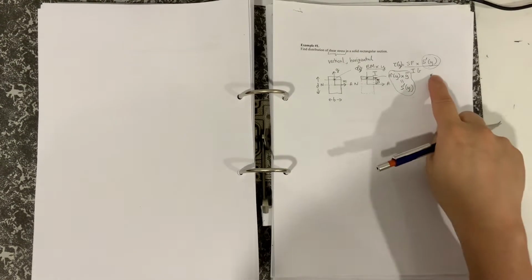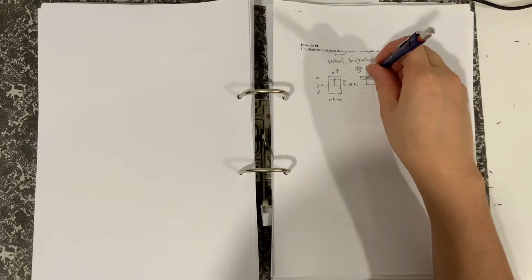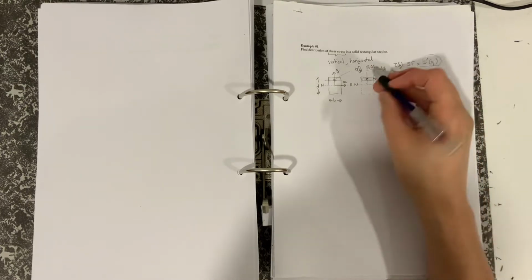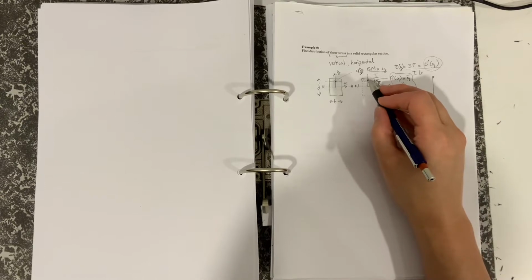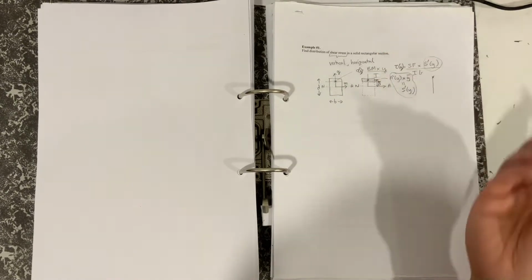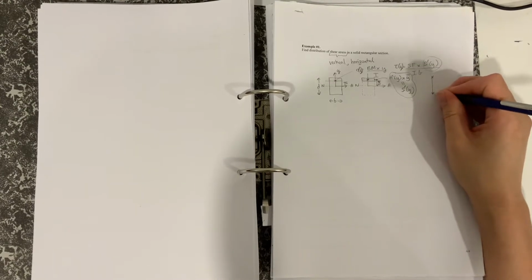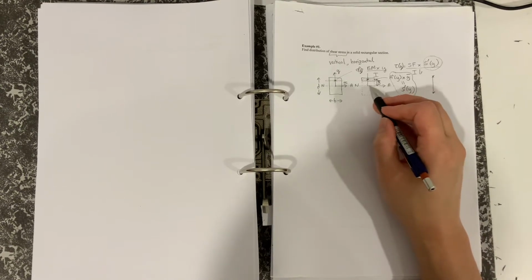And if you're wondering why, think of the longitudinal or horizontal shear stresses. We said the vertical and the horizontal are the same, and at the top surface there's the atmosphere, so it has to be 0. You could make the same reasoning down there, and it is going to be maximum down here.